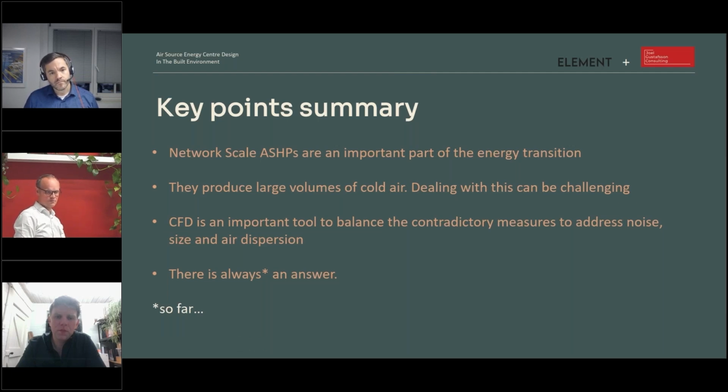We're very transparent about the conservative elements of the approach. For example, the wind is modeled as a static condition. That isn't how it works in practice. Wind is erratic and chaotic. It changes direction and it changes speed. That actually assists dispersion, but we can't resolve the model without having a static condition. So we're very, very clear about this, and we share the outcomes.